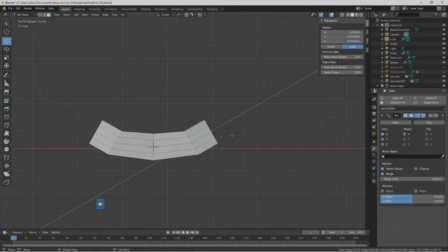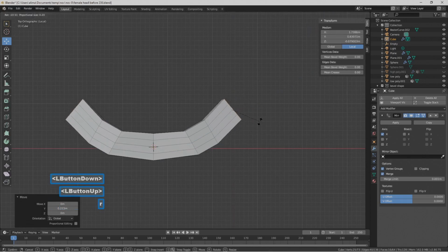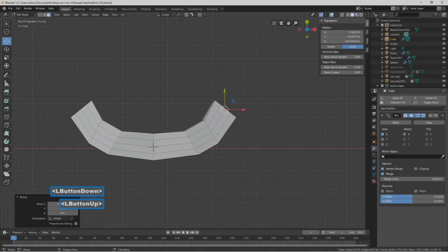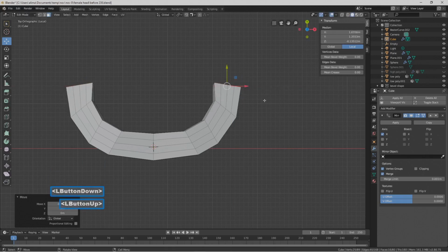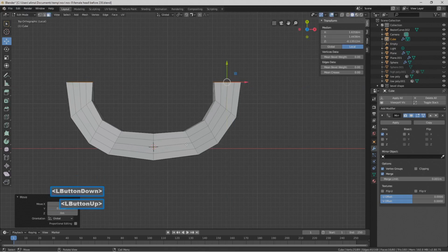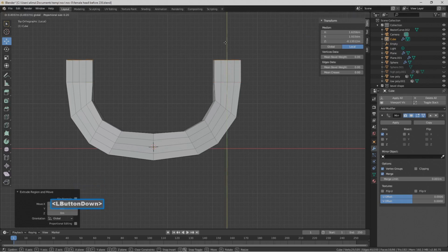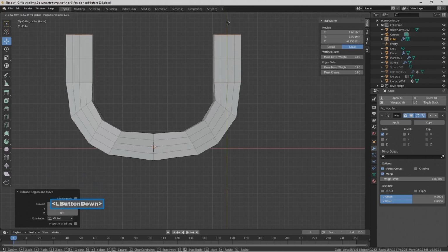So now what I'll do is I'll press E, R to rotate, so there's 3. E, here's 4. I'll rotate some here. I'll press S to scale on the Y axis 0 to flatten that out some. 1, 2, 3, 4. Then I'll press E. 5. E. 6.